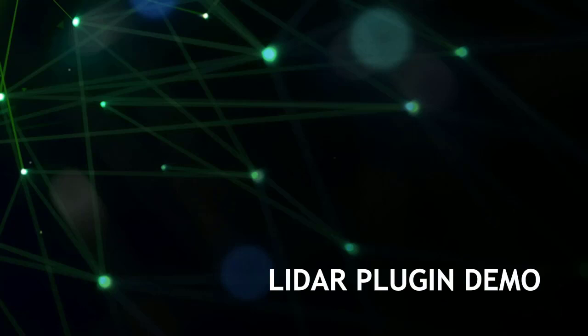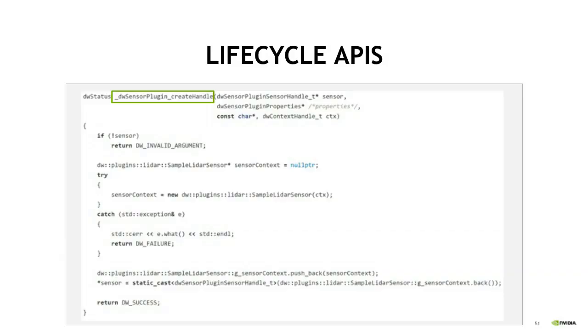Create handle is the function that instantiates the sensor object and returns the handle to the sensor. This function should perform necessary memory allocation to hold the context information for a sensor instance. The handle is passed back to the plugin on each subsequent function call. The memory allocated by this function should be deallocated on a future release call. It's important to note that a user may create multiple sensor instances within a single plugin. This notion of a context or a handle is helpful for supporting multiple sensor use cases.